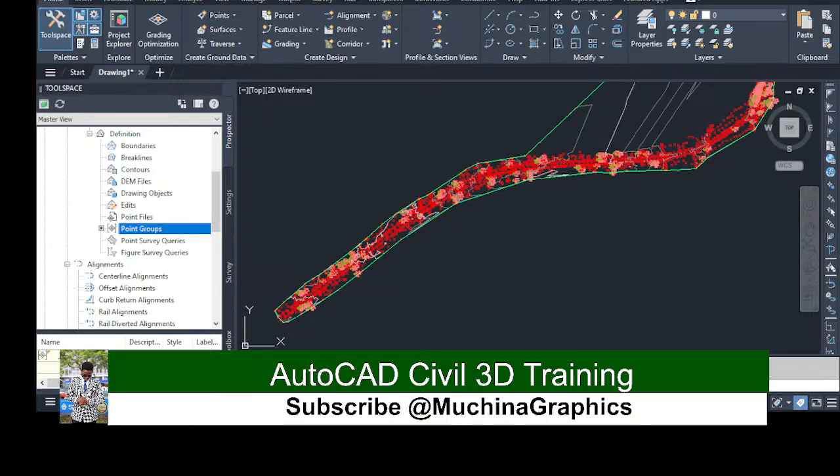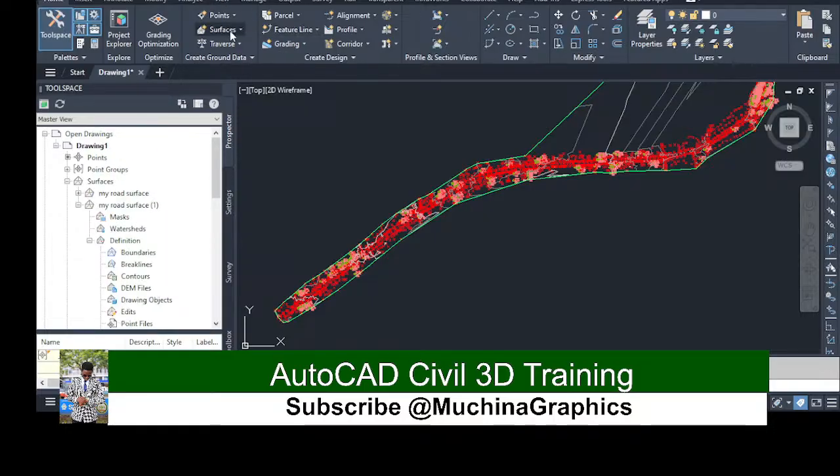So the next thing that I'm going to do is to help you if you are not able to create a surface, let's go back. So the first thing that you need to do is to have already imported your points. And if you are successful in that, thank you, then the next step should be easy for you. So you will go to surface, you click and then you create surface here.